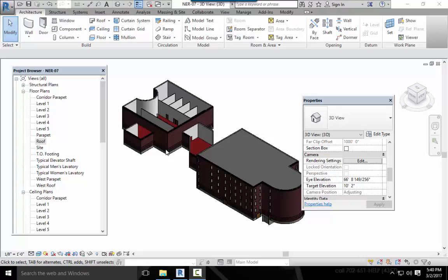Creating a roof by using only the roofing components is necessary, but adding the structural will lead to conflicts when the actual structural model is linked with the architectural model. Also, it's hard for the architect to guess what the depth of the structural framing will be. In Revit, you want each component to be as literal and as true to the model as possible. The second way to look at a roofing system, as you're about to explore, is to build the roof in a literal sense. That is, to create the roof as it would sit on the structural framing by the structural engineer. The objective of this procedure is to create a roof system by adding layers of materials.